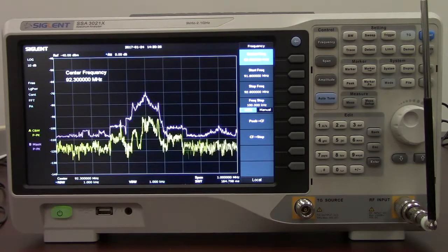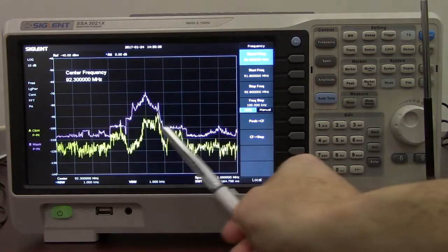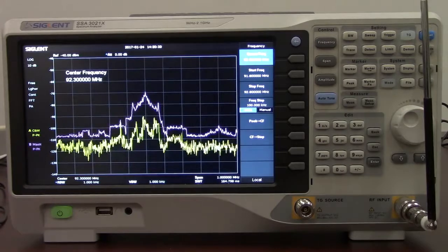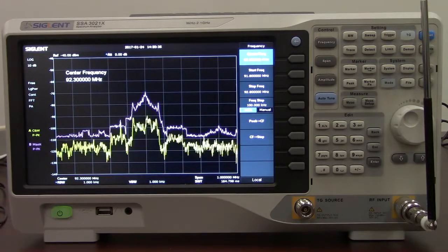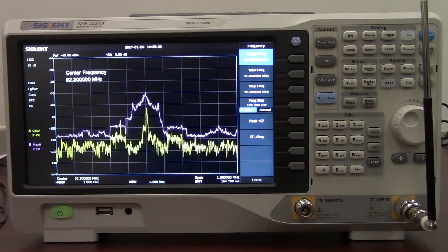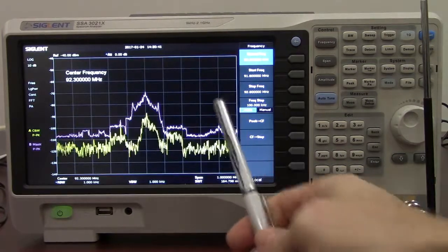So that information is actually held in these side bands on either side of that center frequency. So what we're doing right now is monitoring an FM transmission. Again, this is a useful tool for this particular job because we're visualizing the actual output.